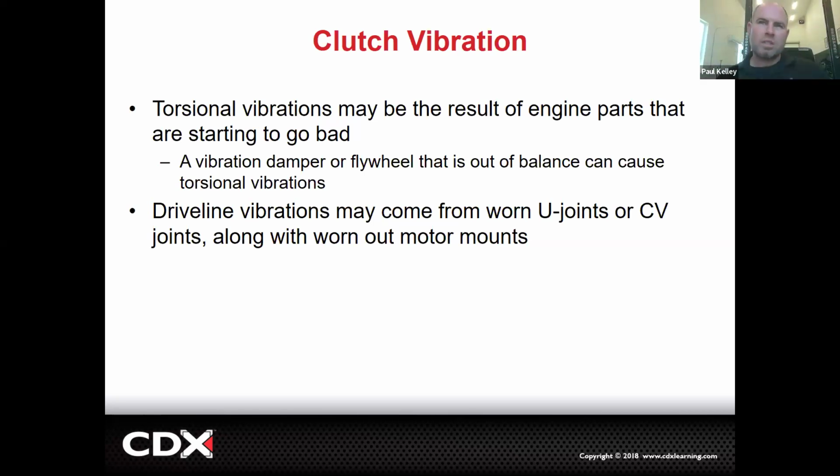So don't necessarily jump right to the clutch, but just know it could be some clutch type stuff, but it could also be a CV axle or drive shaft, which may be made worse by worn engine or transmission mounts that are allowing your powertrain to move and change your angles like we covered last week. That's why that combined unit is for both A2 and A3.